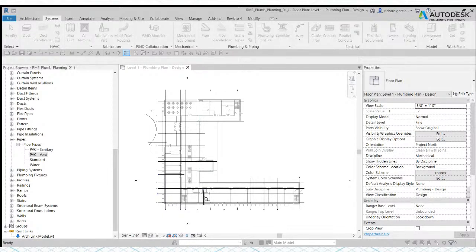I don't know. Is it percent D? I forgot. Okay, so since the settings currently here is in degrees, so no need for you to type the degree symbol. You just type the value and then just click on the next one. And Revit will now read it as 10 degrees. So that's how you change it from here. So you can change that one, the tolerance. So instead of 5 degrees only, you can deviate up to 10 degrees.